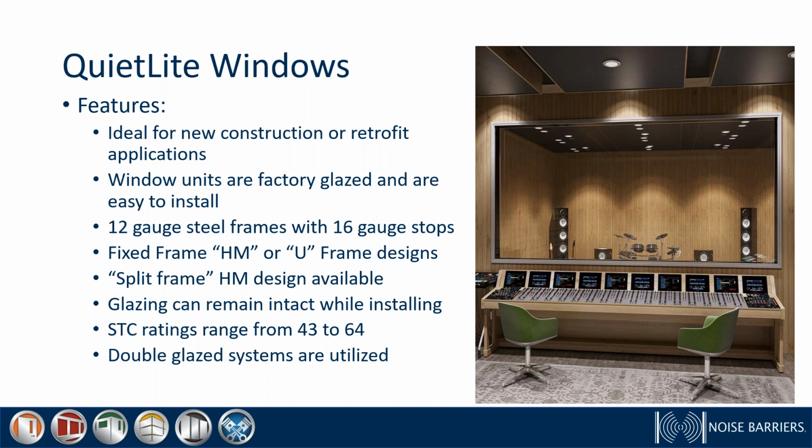STC ratings go all the way from a 43 to a 64. Field performance again is significantly great on this product. Double glaze systems are utilized to achieve the STC rating. The STC rating depends mainly on the opening. You may have a wall opening of maybe 4 inches, 6 inches, 8 inches, 10 and 12 inches. We can accommodate that. It's made to fit the opening size.